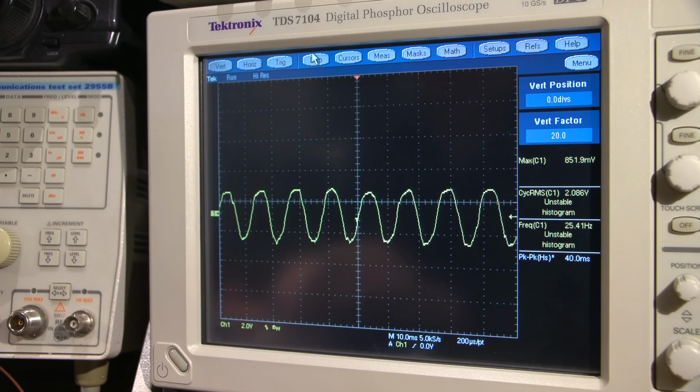And number 8. So if we came to number 8 and we saw the signal missing, we would know that there's something wrong between that, either the capacitor or there's a broken trace somewhere. And that's really common in power supplies and even audio amplifiers, again, that have leaky capacitors that go underneath the electrolytic caps. So power supplies, this is really prevalent because power supplies really work the capacitors hard. So especially switch mode power supplies, I should be saying. So what happens is they leak out of the bottom seal, and any traces that go below or underneath the capacitor, they rot open, and you can't see them because they're sitting underneath the capacitor.